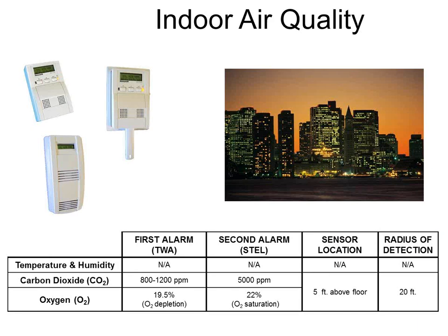Think about it this way. If I've got 10 offices and a conference room, and each office has one person, I've got 10 people. I've got a certain amount of ventilation air I bring in for that space. When all 10 people walk out of their office and walk into the conference room together and breathe in there instead, has my CO2 level at the return air duct changed at all? No, it has not. It's still 10 people breathing on that system. But now I need to get more fresh air into the conference room instead of into the perimeter zones. So I cannot put the CO2 sensor in the return duct on zoned systems. Absolutely cannot do that.